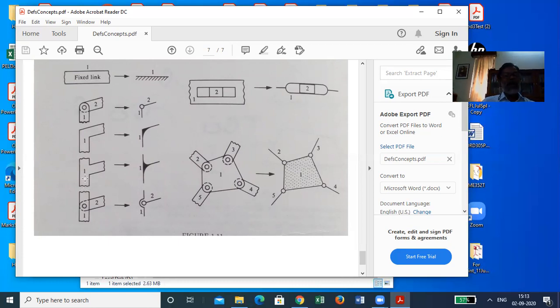Similarly, take a running link which has perhaps some connection here and some connection above, much above this. If a branch of the same link, the physical shape of the body, goes like this to connect to something else, how to show that? You show it by the center lines, and then to show that you have forgotten nothing, that on all three sides it is the same link, you fillet it at both angles, this obtuse angle also and this acute angle also. So now nobody can be confused that it is two links or three links together. Okay?